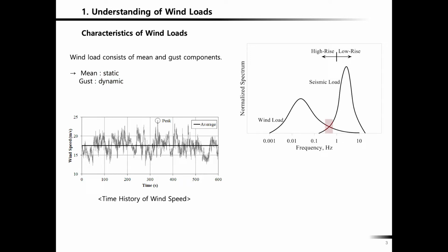So it's more like in this range. For wind load, there are a lot of frequencies here. Here it's a very, very small frequency with a large period. But right there, you see a little bit higher frequencies. And overall, its energy content is focused on a much lower frequency range compared with the seismic load spectrum.